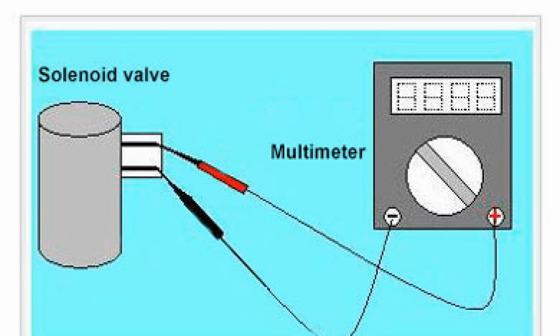Characteristic malfunctions. A big and key role in the long-term performance of the solenoid is played by the quality of the transmission oil itself. It is not necessary to buy the most expensive solenoids when replacing them, if at the same time low-grade lubricant will be poured into the automatic transmission. Therefore, the majority of malfunctions are related to the quality of oil.